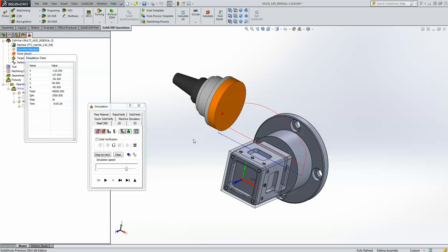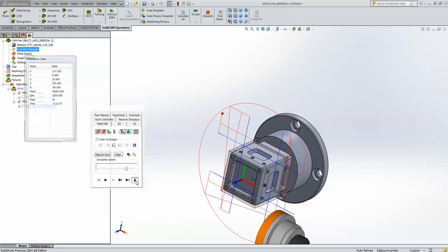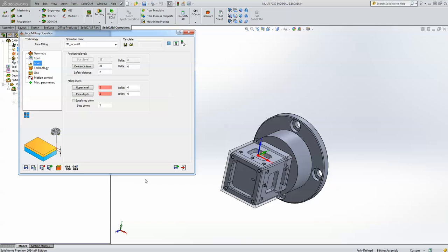And that's why we get the arc exactly the way it does. It doesn't go all the way up to the top. I can set it at any height I want. That's the height I'd like to have it. Now let's run it to the very end, and you can see it works on all of those sides. So what I've done here is I've created in one operation 4 face mill operations without having to use the different home positions that I created before.